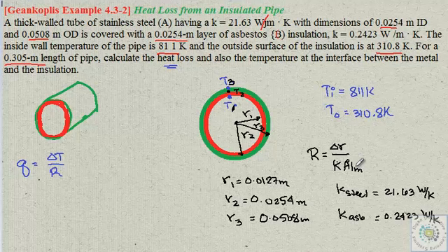Now, I think we are ready to calculate our resistances: delta R, k, area log mean. Oh wait, area log mean first. To compute the area, how do you compute that? What is the area, the inner area, looking first at the steel pipe? So let's focus first on the steel pipe.